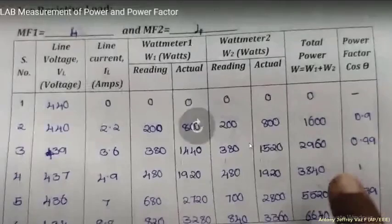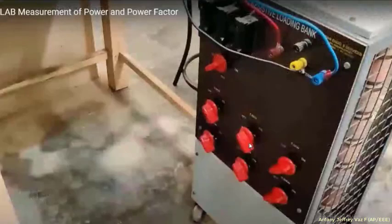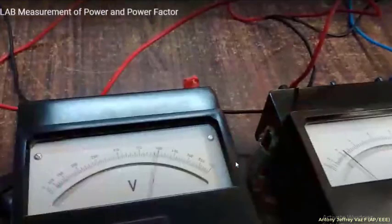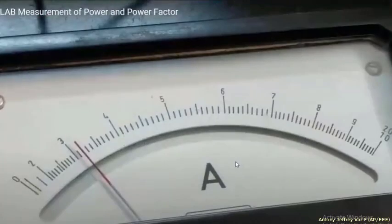Similarly, you need to turn on each and every switch. First you turn on this switch and take a reading. After that, you turn on this switch. You should not turn off the previous switch; you should keep it in the on position. So this will add 1 kilowatt. After that, if you turn on this switch, it will add 1.5 kilowatt. After that, if you turn on this, it will add 2 kilowatt. Similarly, you should turn on each and every switch consecutively, take 6 readings, and note the readings in the tabular column.